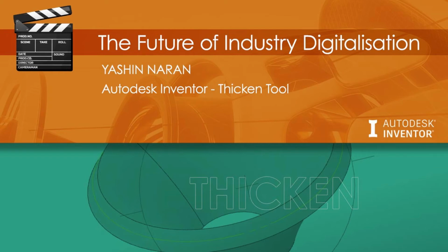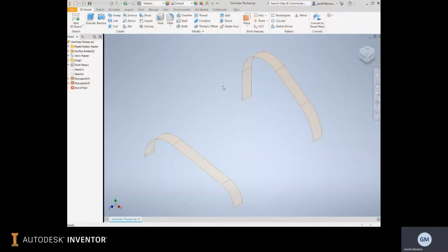YouTube series. In this session, we're going to take a look at the surface thicken tool. So in the case of surface thicken, we're going to construct the surface, and then we're going to take a look at how we generate 3D volume out of that technically infinitely thin surface. So surfaces are essentially a thin representation of a curve, and that curve then needs to be generated into volume in order to be able to either cut it or machine it or create a mold out of that.